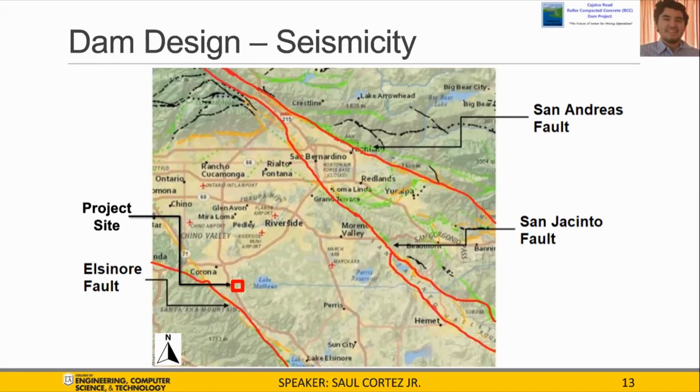The geotechnical report for the Lake Matthews outlet facilities, prepared for the Metropolitan Water District of Southern California, was used to characterize the subsurface geological profile, since the site investigation is located 2.6 miles away from the proposed site location, making it a good estimation of the geological conditions at site. Most of the material found is granite, followed by diorite, with a marginal percentage of other materials.